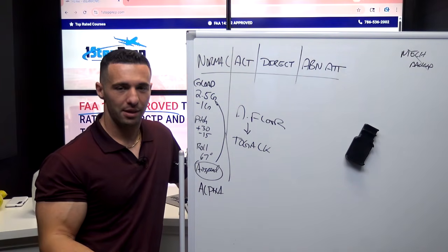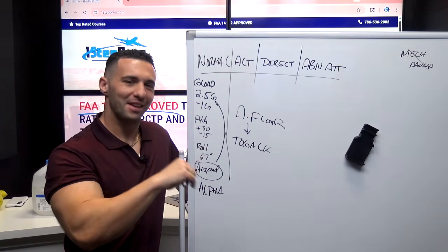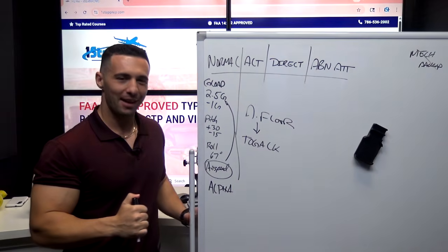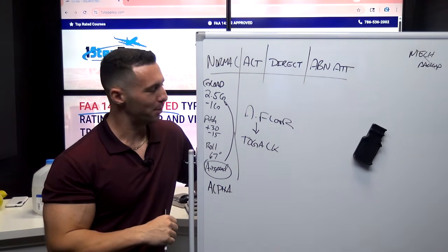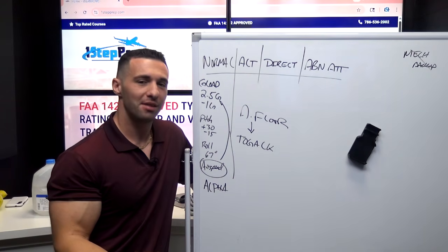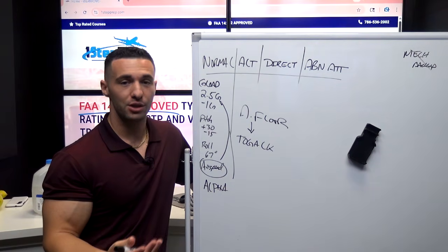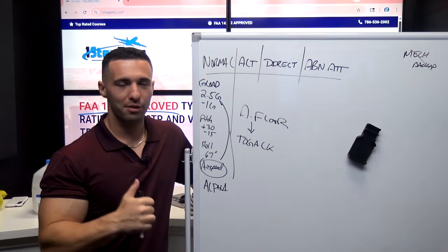And the way typically that we disconnect auto thrust, of course, is via the disconnect push button, the instinctive disconnect push button, whatever they call it, I don't know. You hit the IDP, and when you hit the instinctive disconnect push button, it will disconnect the auto thrust. Now, there is another way to disconnect the auto thrust, which is effectively to reduce it from the active range, which would be basically back to the idle position if I bring the thrust levers back to idle.